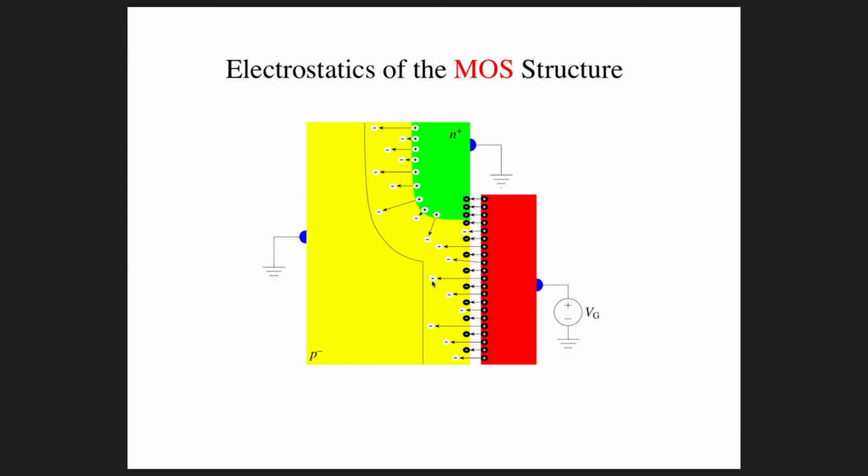And so there's a couple of things to note here. We call this range of gate voltages between flat band and threshold subthreshold. This is the region of gate voltages where we're basically creating this depletion region, bending the bands down, and creating a nice low energy spot up at the surface.